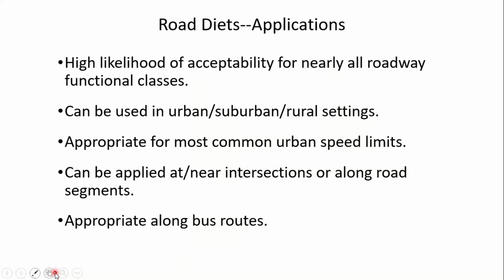Applications: high likelihood of acceptability for nearly all road functional classes. Can be used in urban, suburban, or even rural settings, and appropriate for most common urban speed limits. You can apply these at or near intersections or along road segments, and they are appropriate along bus routes.